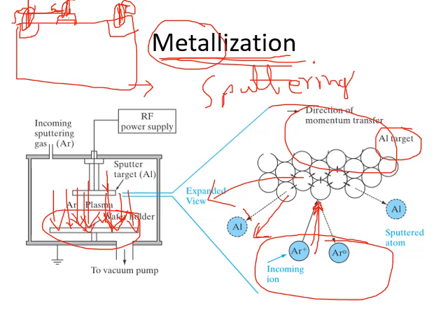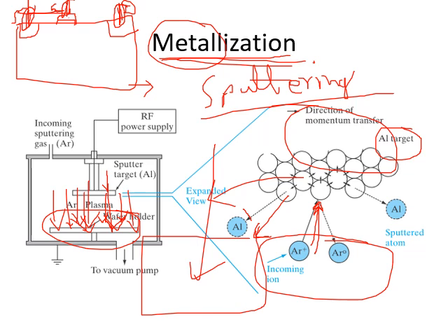Why? Because if we go with the sputtering technique for copper, copper will not stick onto the wafer, it will get inside the wafer. Diffusion will happen. Copper will not come and sit on the surface, it will get inside the substrate, and then it will change its property.